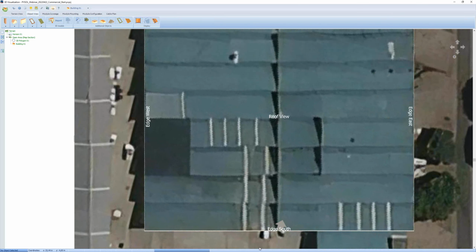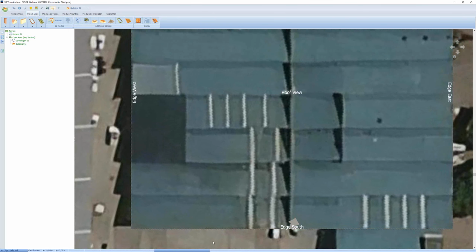And therefore, again, you can also use this polygon tool on a building. Yes, not just to draw the buildings on the map. So also if you have some texture on a building, you can just activate the building and also use the polygon for it. Yes, for substructures, for shading objects or bad areas, and also if you would like to add a further building or 3D object on top of the roof.